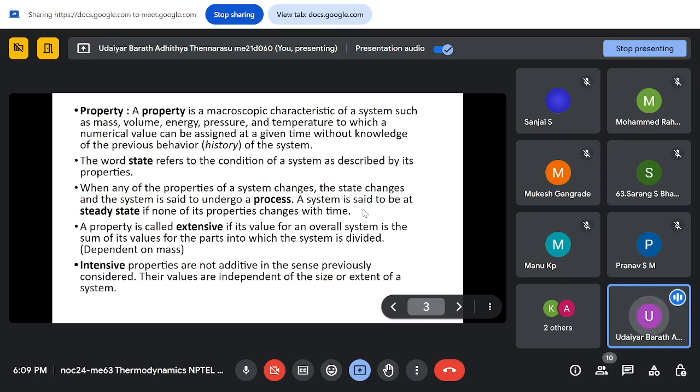Generally speaking, if you don't know a property, you can try to visualize this case, try to split it and see if the property will change. If it doesn't change, it's an intensive property. If it changes, it's an extensive property. And any extensive property can be changed to an intensive property by dividing by the mass. We'll be using those in the coming weeks. Just as a heads up, you can find an intensive property from an extensive property by dividing by mass.